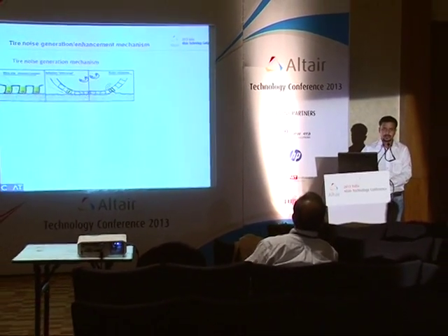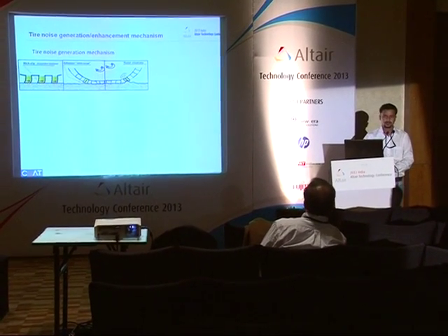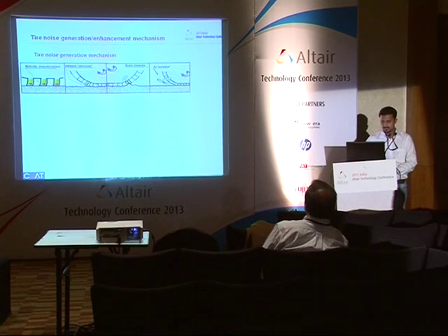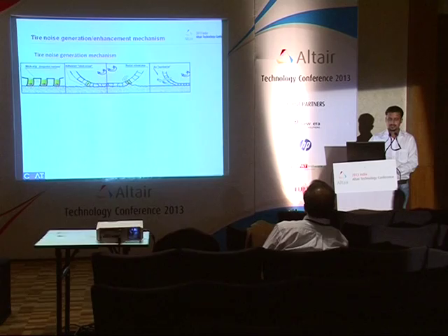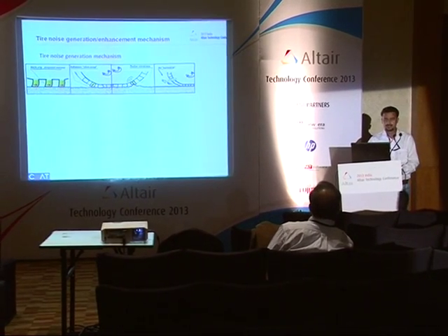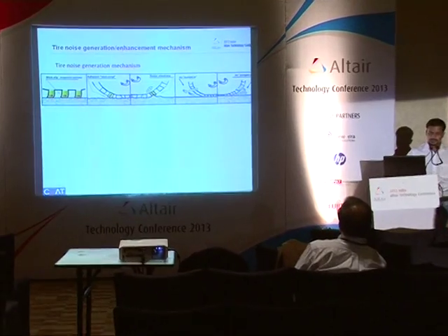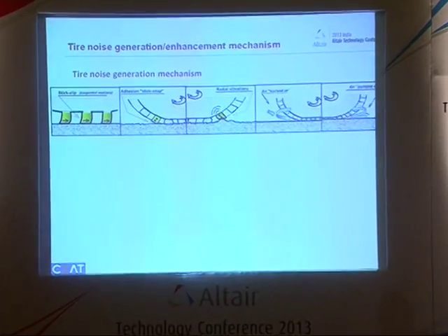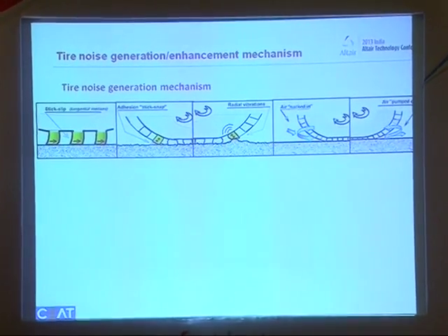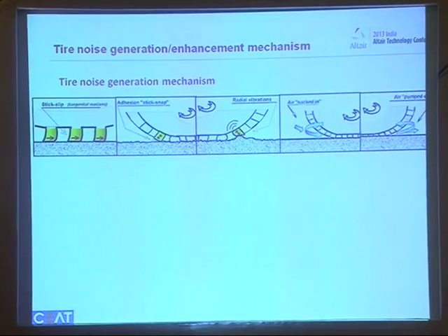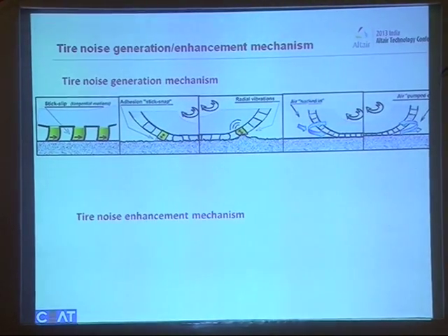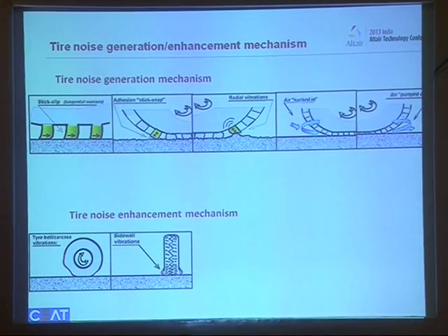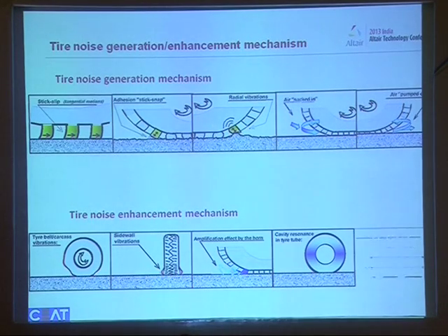Whenever the tire rolls over an obstacle, it causes radial force variation. That is a vibration and hence noise. When a tread pattern comes into road contact, the voids and grooves try to suck air inside. Similarly, when it leaves the road contact, this sucked air will be pumped out. This air sucking in and pumping out also causes noise, that is air pumping noise. This noise generated will be enhanced by some mechanisms, which are nothing but resonance. So this will enhance the noise.